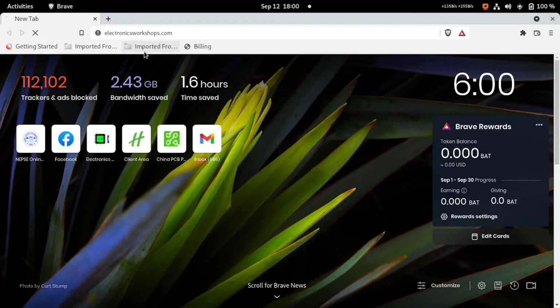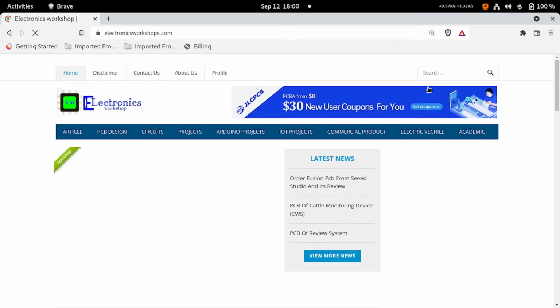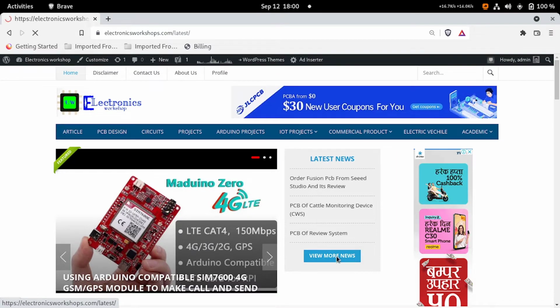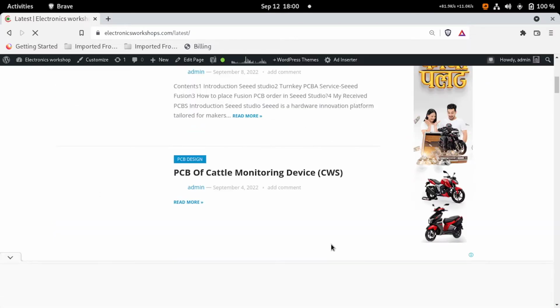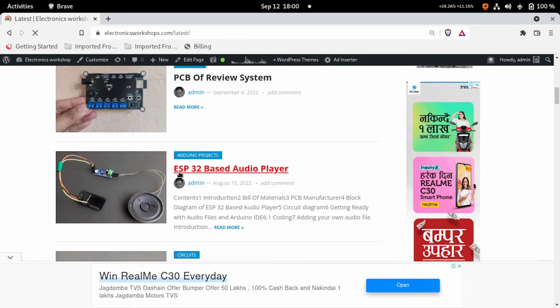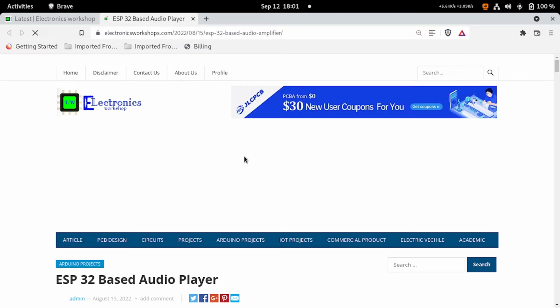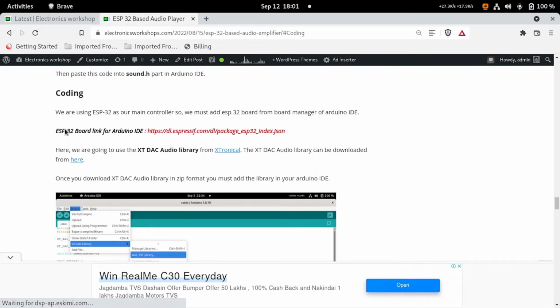First of all, go to my website, electronicsworkshops.com, and search for this project ESP32 based audio player. I will also place a direct link of this project in the description of this video. Open this project and go to the coding part. You can see ESP32 board link for Arduino IDE. Copy the link and come back to your Arduino IDE.